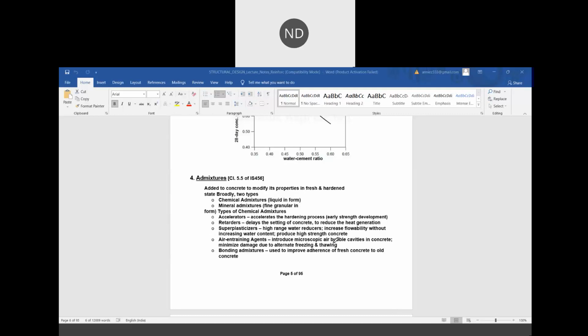Previous experience with the data on such materials should be considered in relation to the likely standards of supervision and workmanship of the work being specified. An admixture should not impair the durability of concrete nor combine with the constituents to form harmful compounds.